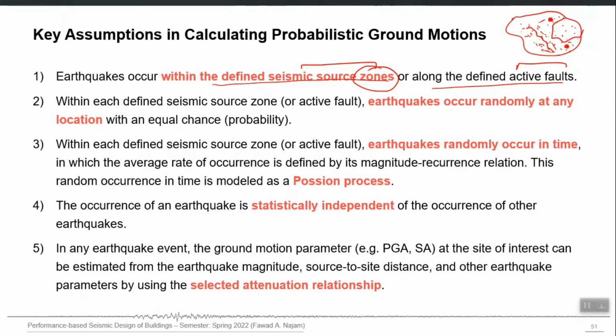and I will treat that whole area as a source, as something which produced earthquakes in the past and which can produce an earthquake in the future also. So the whole area, let's say this shaded region, will be declared for the purpose of PSHA as a source. This is a more convenient concept because for most of the earthquakes in several study regions, you may not be able to attribute them to a particular fault.